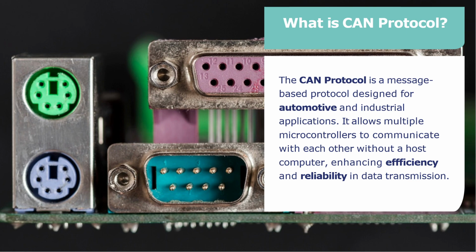But in other protocols we must have a host computer, and then only it will communicate with the other ECUs. But even if you do not have a host computer, this CAN protocol allows communication between these ECUs or different types of microcontrollers, enhancing the efficiency and reliability in the data transmission.